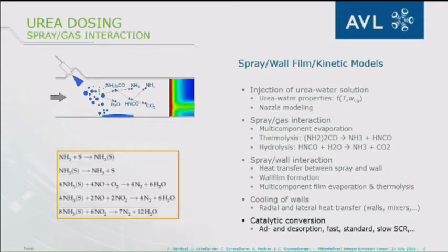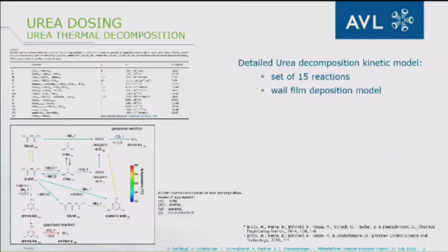Then moving to the catalyst. In the catalyst, the whole process of NOx conversion needs to be simulated, considering the ammonia adsorption, desorption, then the fast, slow, and standard DeNOx reactions.